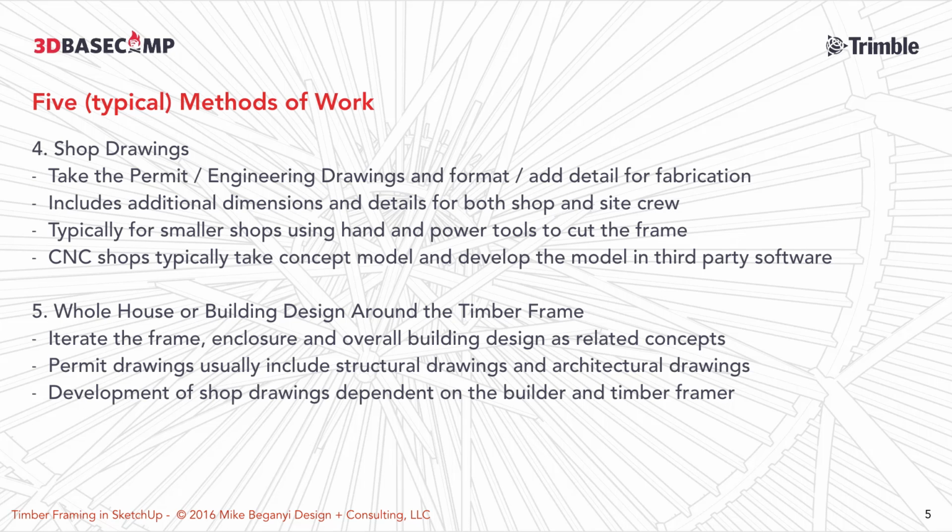Some of the larger companies will use HSB CAD, which is an AutoCAD overlay, and that'll generate machine code to run a Hundegger or a Swiss CNC machine that'll do a lot of the joinery. Some of them will use CADwork. CADwork actually has a thing now where you can import a SketchUp model directly in. In these cases, I'm generally not putting any joinery on. It's basically pretty assemblages of boxes, which is what SketchUp is really good at. It's really good at drawing rectangles and long boxes.